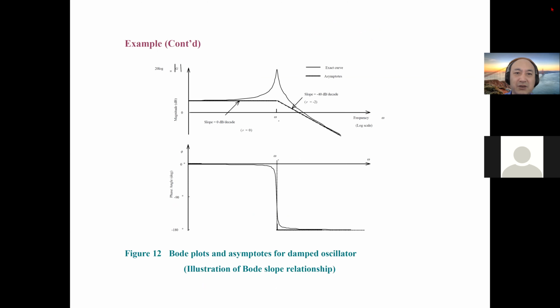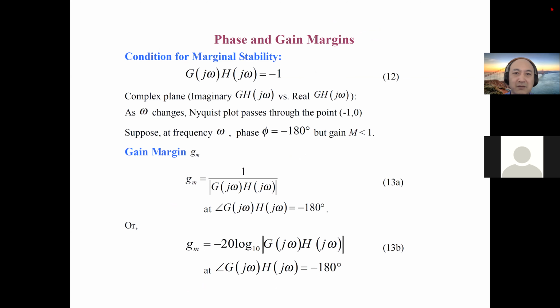In the Bode magnitude, when we talk about second order, you have a resonance peak. Otherwise, you will have different behavior like that. But remember, the slope here is minus 40 dB per decade. So today, this is a very new concept. Again, we need to answer how to check the stability and gain and phase margin.